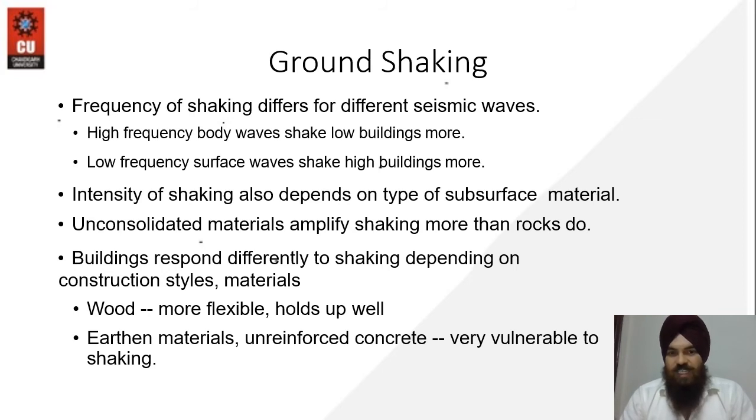Then about unconsolidated material, which has not been consolidated yet. Unconsolidated material basically amplifies the shaking more than rock. So if the structure is resting on hard strata or rock strata, it will definitely give more stability to the structure. Then buildings respond differently to shaking depending upon construction style and material.